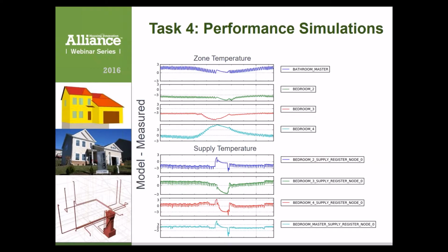Yeah, so what we are simulating is exactly what's installed up at the lab house today, and that is a single zone variable capacity furnace. In the bottom left of the slide, you'll see a rendering. It's somewhat small, but it actually shows the physical duct layout, kind of in an X-ray view of the house. So to that extent, yes, it is single zone at this point. We're really just trying to confirm that the model is accurately capturing the detail, the different transient phenomena that is happening in the real world up at the lab house.